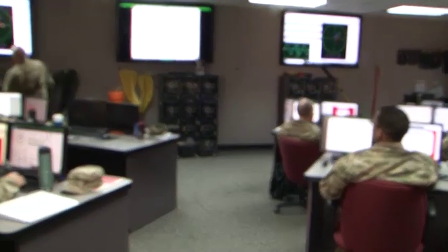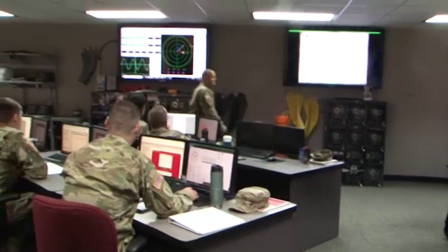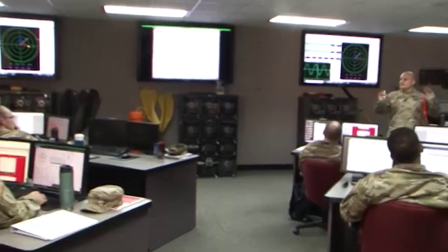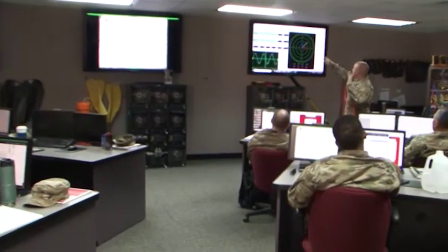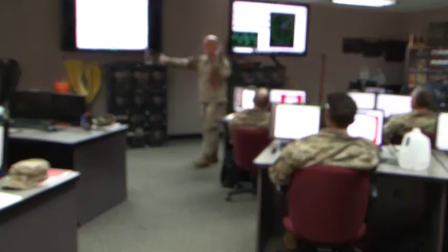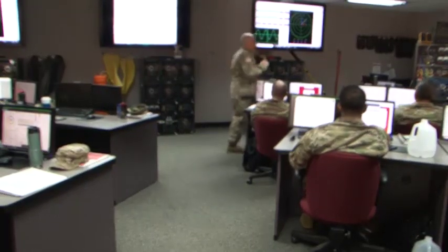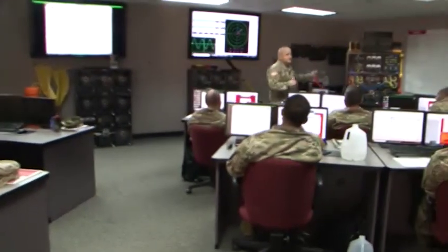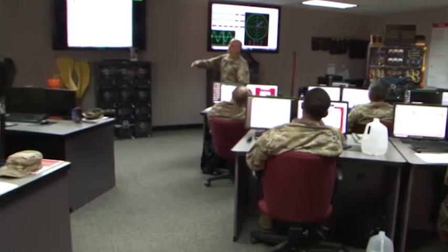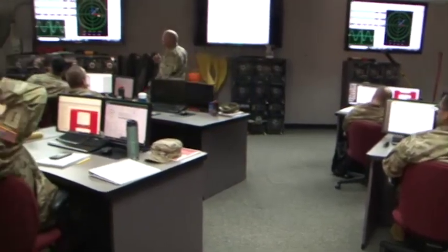And we see our phase here. We're at 43 something there on the voltage, and that's for some other varying reasons, but the important thing to understand is those two things are not summing like they did in a regular circuit. There's angular orthogonal differences in the relationship between that inductance and that resistor that's causing this. You're going to do something very similar to this in 5.1, I believe, and you're not going to know why. You're not going to do any further math on it to deduce some things, so I want to give it all to you up front.